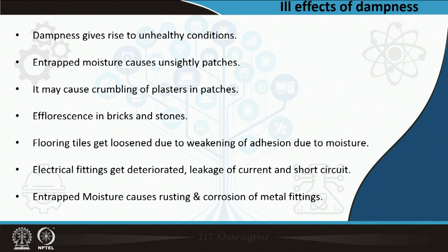Similarly, if you see some bricks experiencing efflorescence, that is salt patches coming out, then you must immediately think that the building is experiencing damp from some point. If you are curious, and have the training and expertise, you can find out the source, and immediately correct it with the different methods which I have just talked about.